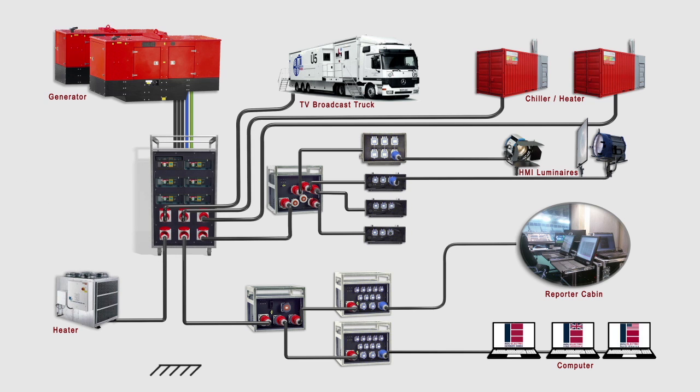The snag is that an RCD cannot distinguish between the capacitive leakage currents that occur in normal operation and are caused by the capacitance of lines and filters on one hand, and dangerous resistive or ohmic fault currents on the other. Nearly all electronic devices, as well as equipment operated with ballast devices, cause capacitive leakage current. Additional ground leakage is caused by the capacitance of lines and by the line filters needed to fulfill the requirements for electromagnetic compatibility, or EMC.